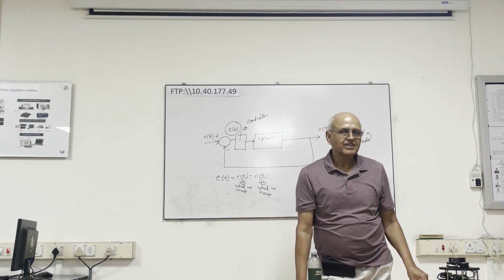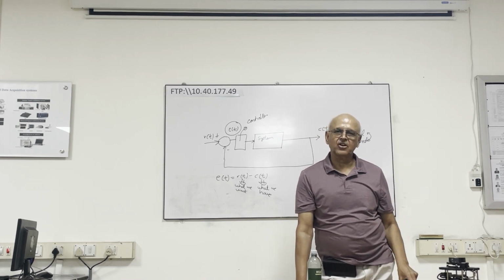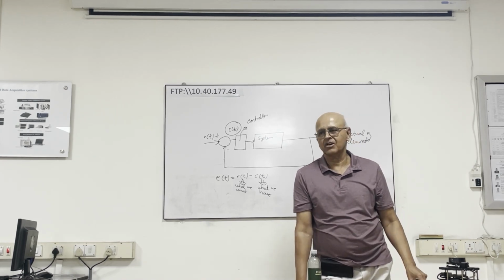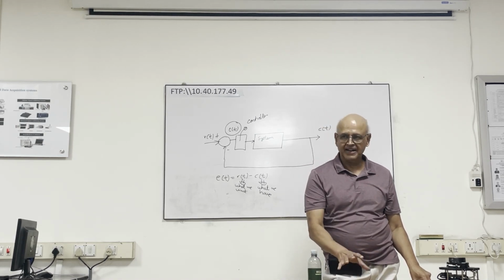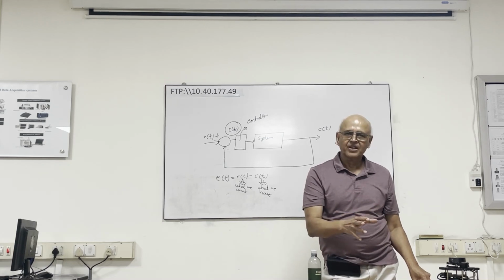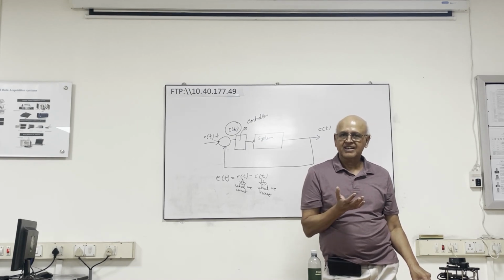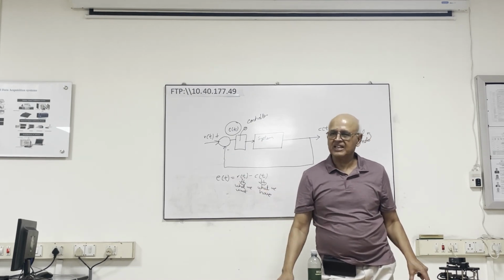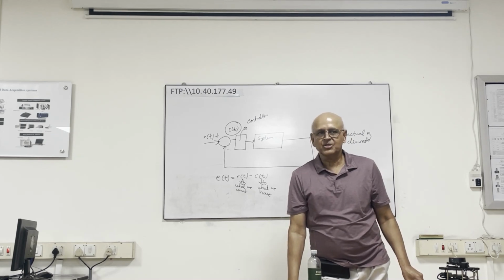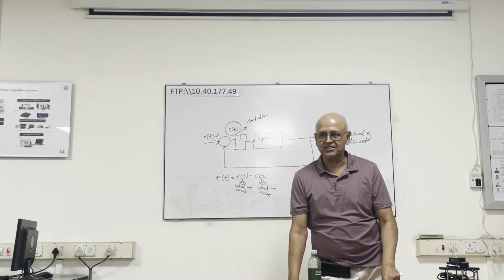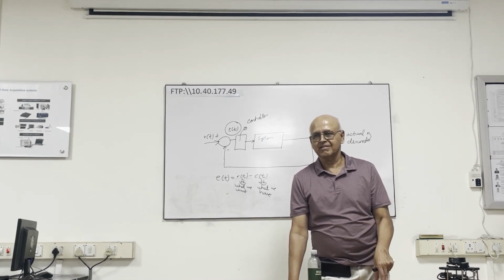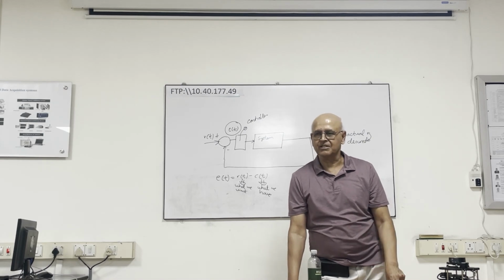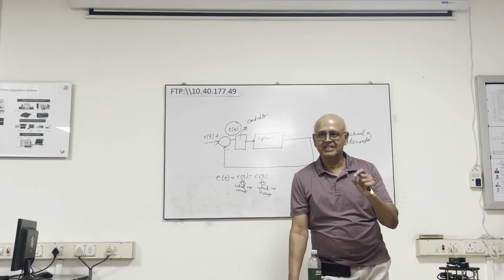Not really. When you drive a car on the road, next time try to maintain a constant velocity. Even the cruise control system cannot maintain a constant velocity, because the road surface is uneven, right? Sometimes it's rougher, so velocity will drop, and then the control system will act and push it up again. But that means the average velocity cannot be constant. So the only way you can ensure distance is by monitoring distance, not by monitoring time, because that assumes that the velocity is constant. So you have to monitor distance. The loop has to be driven by distance of travel.